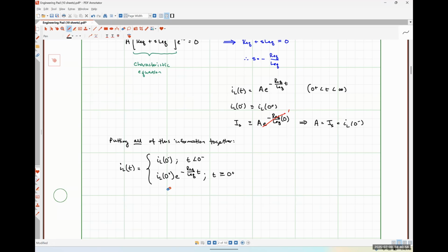Now, when we defined this function earlier, we defined it over the interval from 0 plus is less than t is less than infinity. And I've effectively thrown the infinity away when I wrote it down here. Well, that's because we have exponential decay. So we know that over time it's going to settle down to 0. So what it's doing after t is equal to infinity is the same thing that it was doing if we just let t get large enough. So I haven't lost any information by representing it in that way either.